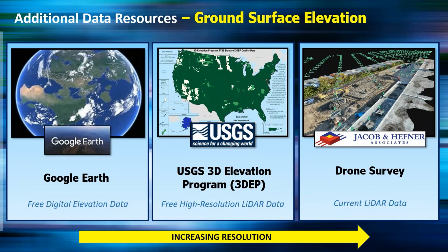Your next best option is the USGS 3D Elevation Program, or 3DEP. This has free high resolution LiDAR data that's collected, I would say, generally every 5 years. Some areas of the country it's collected more frequently, others less. This is fantastic data. The government has spent millions of dollars collecting LiDAR data consistently across the entire United States. It does take some processing to make it into a usable format. If you need help, I can help with that. Know that it's out there.